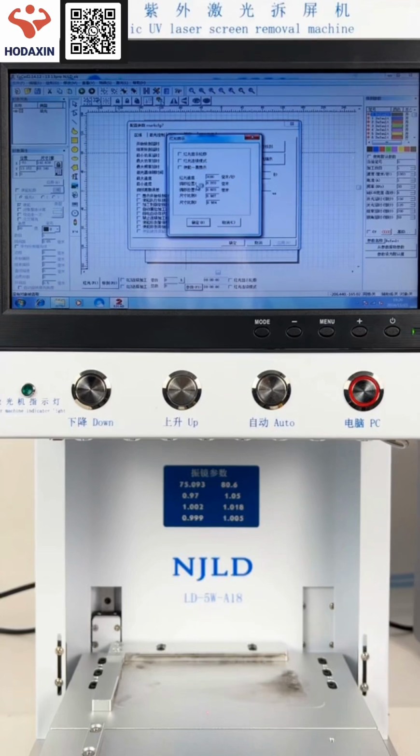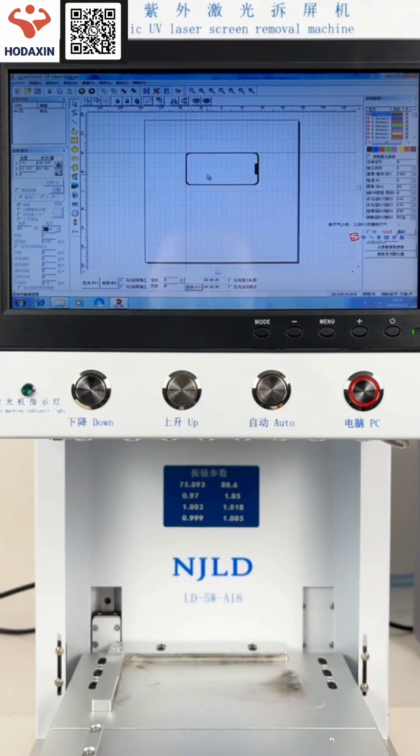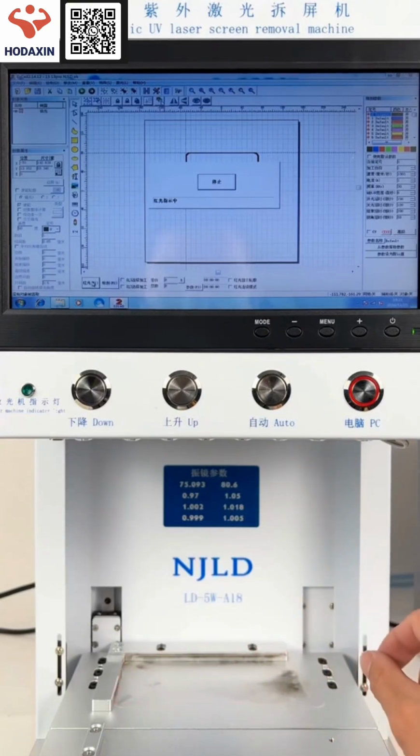The red light X displacement, Y displacement, and scale can all be calibrated very accurately through the parameters here. For example, if I mark a square in this place, as long as the red light aligns perfectly with the square, then the red light calibration is considered complete and you can save it directly. This is about how and where to calibrate the red light.